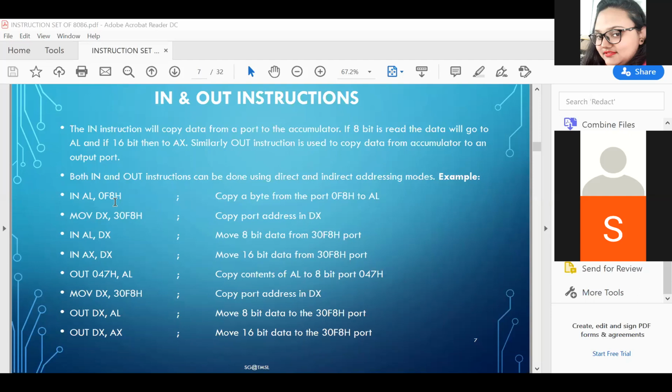The microprocessor only identifies the address of that particular device by which it is connected. So something that can be read is read from the address, and something it needs to write must be written onto the address. So the address is the main part by which the microprocessor can identify each device.